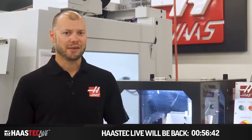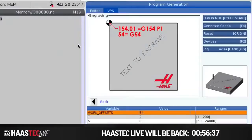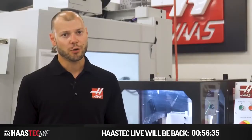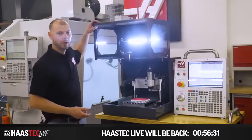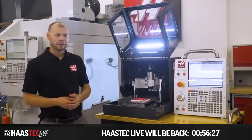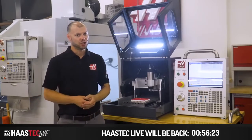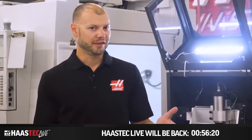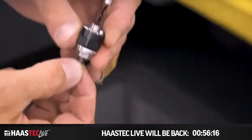I want to show you how easy it is to set up the desktop mill and use VPS conversational programming to generate some code. So you can see here, I have a couple blocks of plastic on the table to work with. We mostly recommend cutting plastic or machinable wax on this machine since the material is cheap and reduces damage if a crash occurs. Or, for the ultimate in simplicity, we offer the spring-loaded pen attachment which mounts directly in the